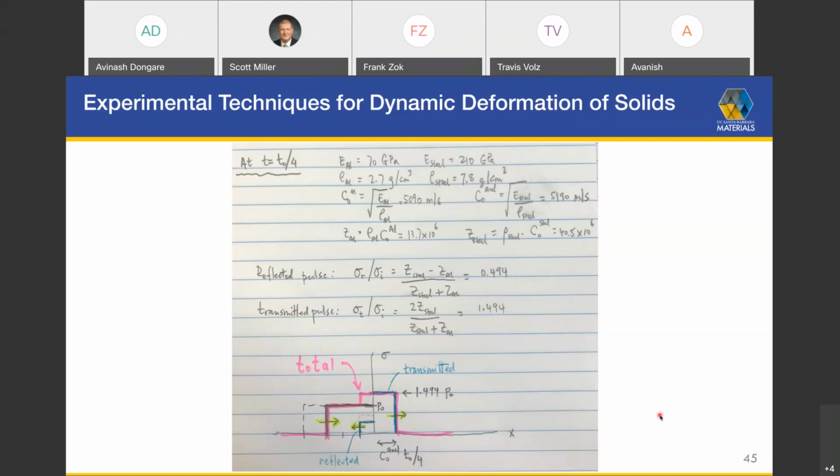Now, if you were to look super, super carefully at the loading and the unloading curve, you might find there's a tiny bit of hysteresis. There may be friction effects. There may be some dissipation due to small amounts of dislocation motion. For most engineering materials, that's almost imperceptibly small at the kinds of temperatures that we're interested in. And so we're making the same assumption here.